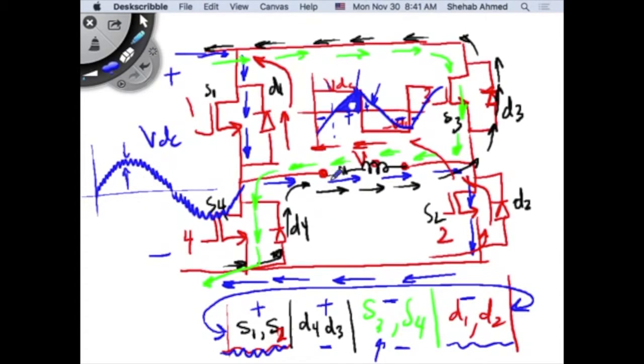Yeah, in this case, I was just talking about the RL load. But if you want to control, here I'm not really controlling ripple because I'm switching once per period. So this is my output current, my peak-to-peak output current. I don't really have the notion of ripple in this case. But here, my peak-to-peak output current, for example, is this, but I have ripple here that I would like to maintain within a certain window. How do I achieve that? I cannot achieve that with fundamental frequency switching.